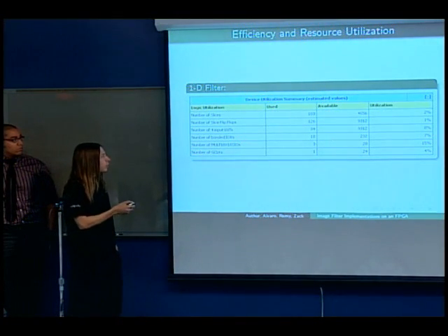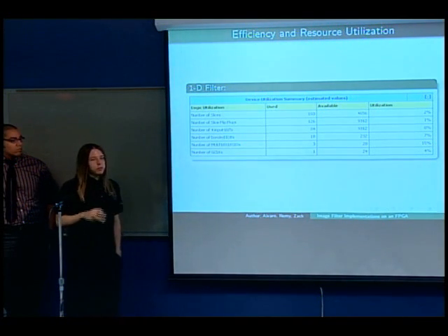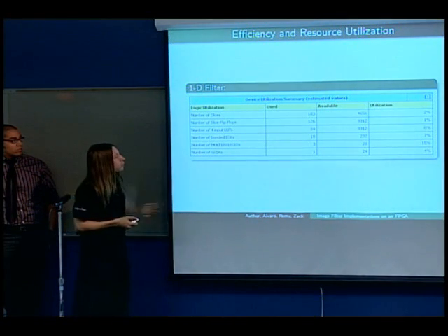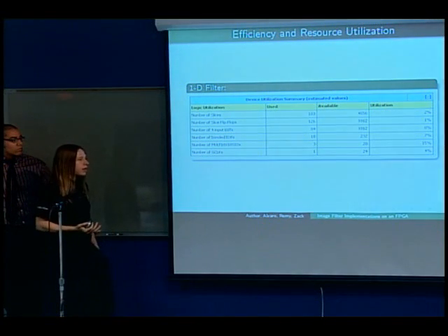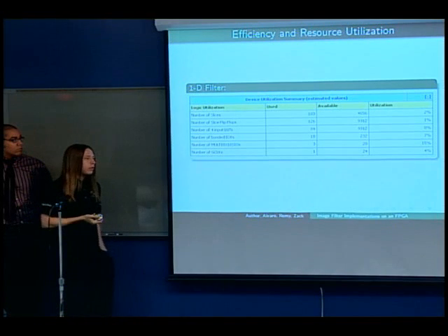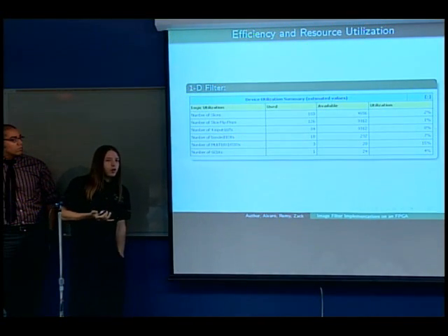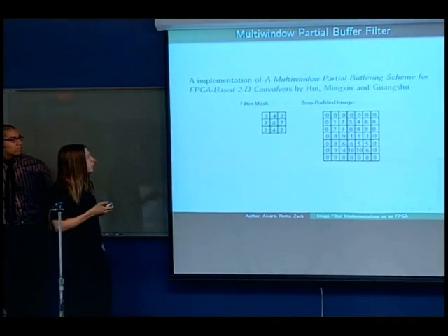And this is our final 1D filter, well, convolver. And assuming we use 2 of these in a non-pipelined architecture, which would be 2 cycles per pixel, then we could only use about 10% of the resources to do an image of virtually any size. But that's 2 cycles per, and we'd rather do 1. But the quicker your code runs, the more memory it's going to cost. It's almost inevitable in computing.